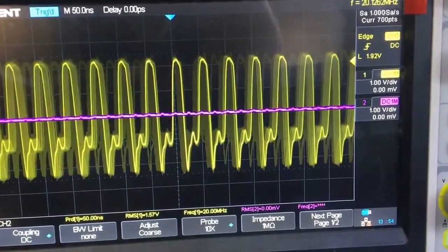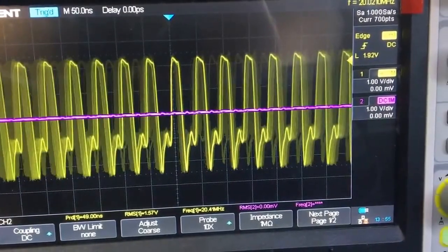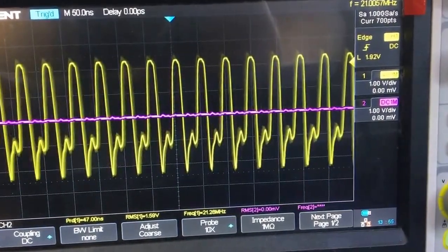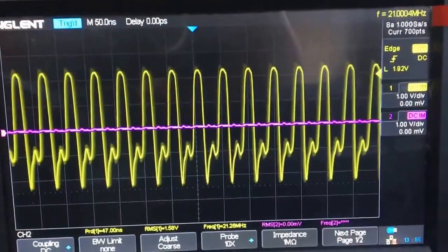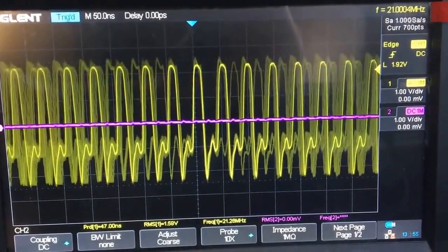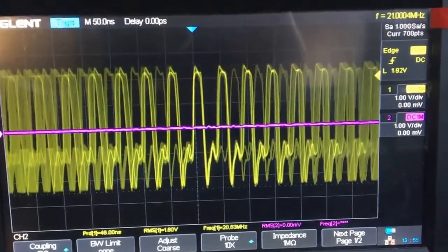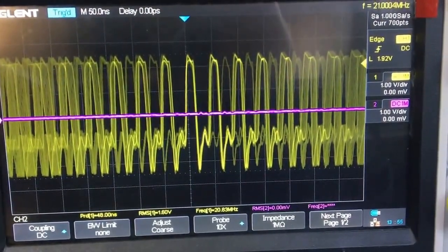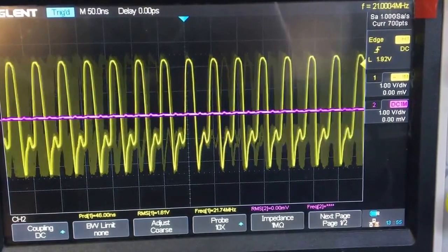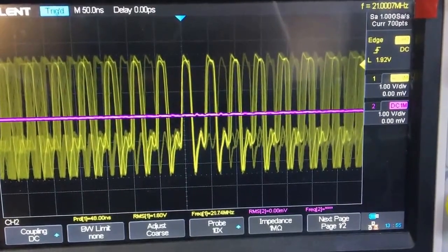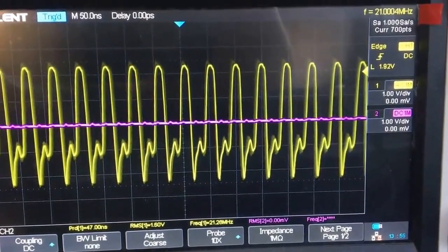So what I think that is, is noise from the VCO coming through. That's the best one there, and that is on 80 megahertz and actually doing 80 megahertz. Whereas that's 60 megahertz and actually doing 80 megahertz. So they should be the same in theory, right? If it is a control fault, it's not, is it? So that's the same frequency, 80 megahertz there, 80 megahertz there. The noisy one's the errored one.